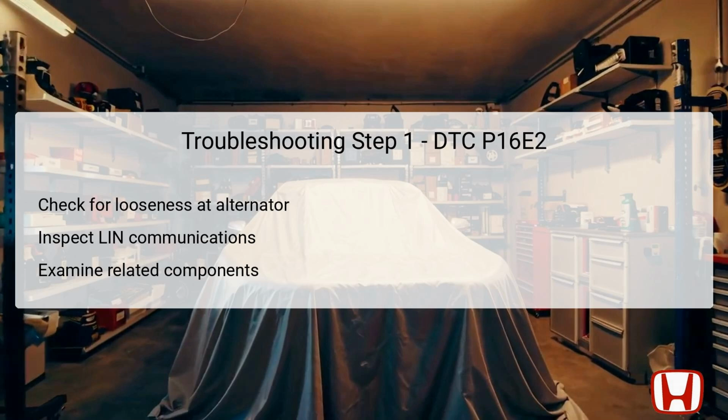Additionally, all related components, such as the 12-volt battery sensor and DC-DC converter, should be evaluated for proper connectivity and functionality. These steps not only help pinpoint the issue, but can also prevent further complications if addressed immediately.